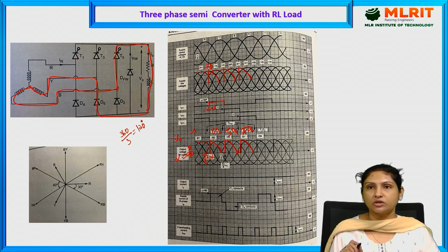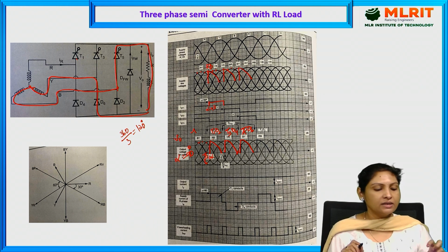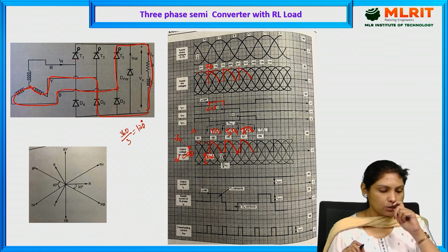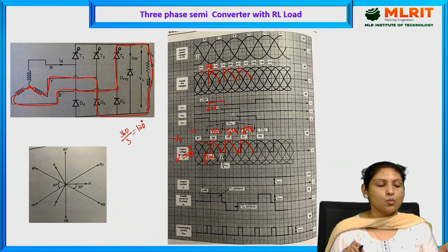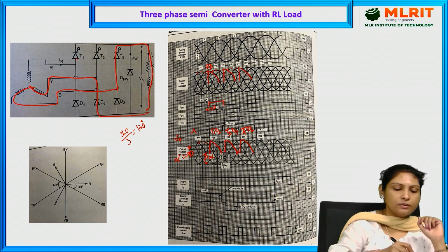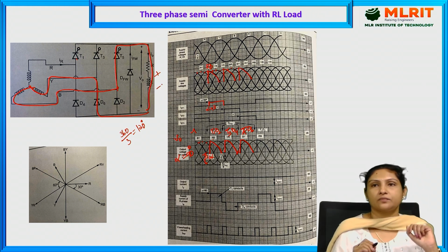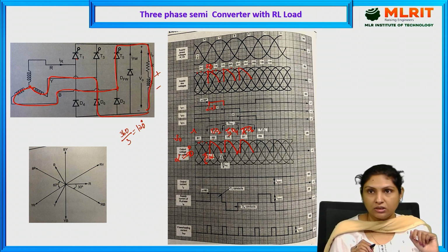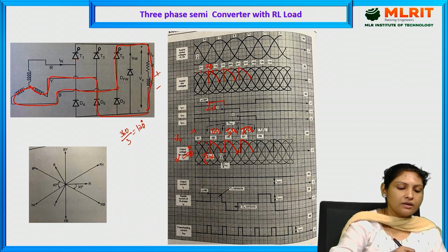Similarly, let us check the output current waveform. Since we are making use of an inductor, an RL load, while load current is flowing through the inductor, the polarities across the inductor will be positive, negative. By the time the positive half cycle is completed, a certain amount of energy is stored in the inductor, given by VL equal to L into di0 by dt.